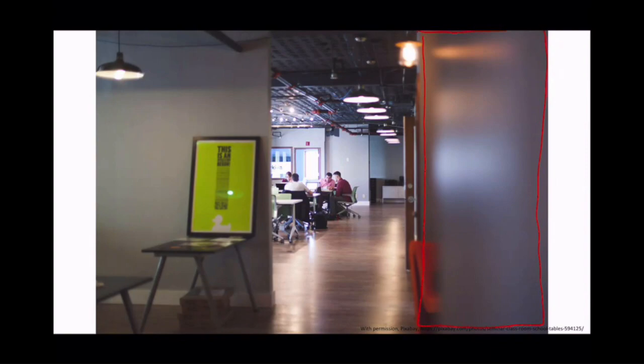So that they meet all the requirements. Now, is that good? Yeah, it's nice not to have to. You always can, but if you have to, not only do you have to assemble it in a way that has been tested to meet the number of hours that the table requires, but all penetrations from pipes and conduit and ducts have to be sealed. You have to put smoke dampers inside the duct to make sure the smoke doesn't move its way through.